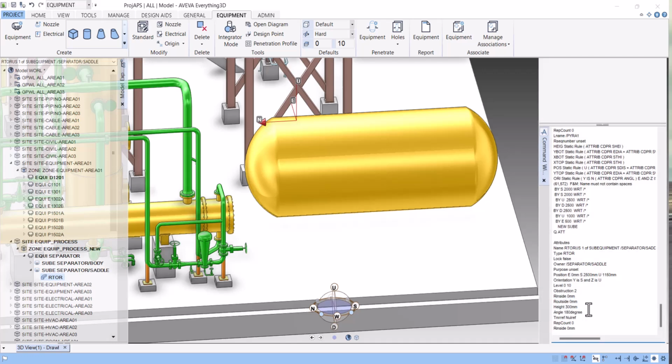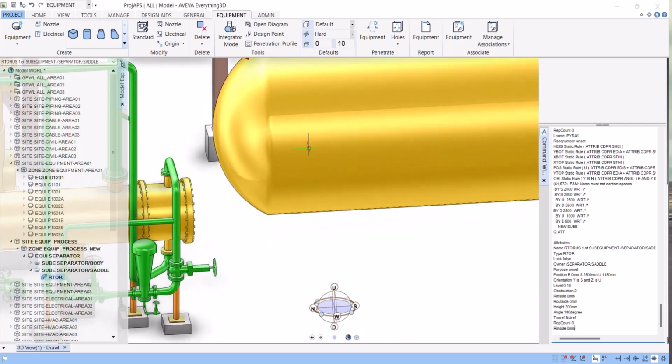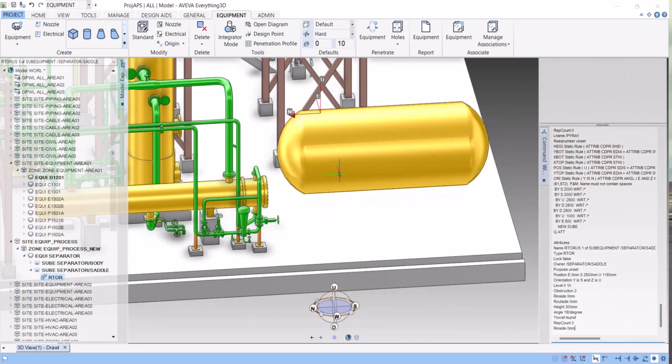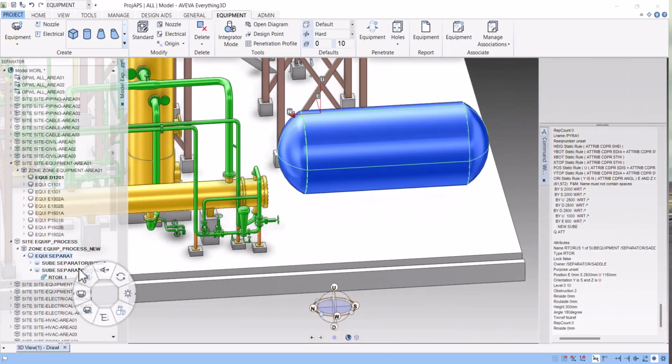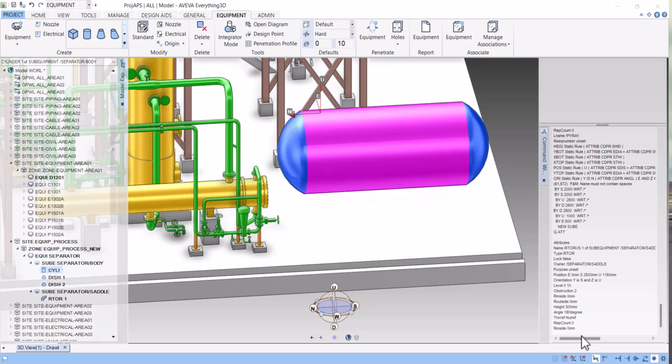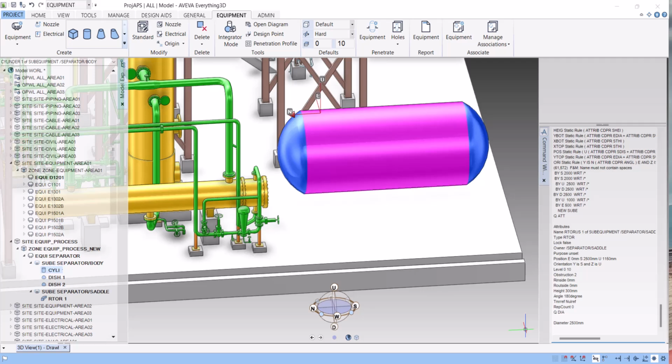So we will click on R inside radius. What is R inside radius? R inside means the OD of this shell. So the OD is how we check here. If you click here, click on cylinder and type here, if you forget, dia. So dia is 2.5 meter.